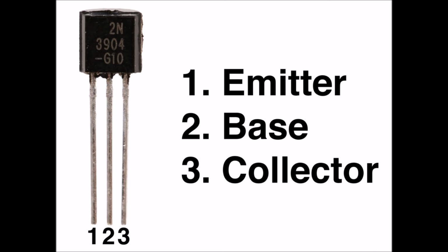Operating point. In electronic engineering, establishing an operating point is called biasing. Biasing in electronics means establishing predetermined voltages or currents at various points of an electronic circuit for the purpose of establishing proper operating conditions in electronic components. Many electronic devices, such as transistors and vacuum tubes, whose function is processing time-varying AC signals, also require a steady DC current or voltage to operate correctly.